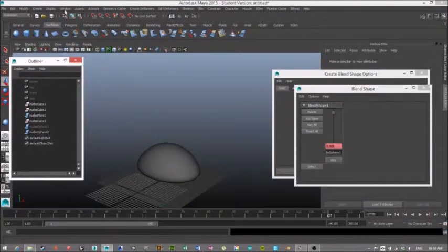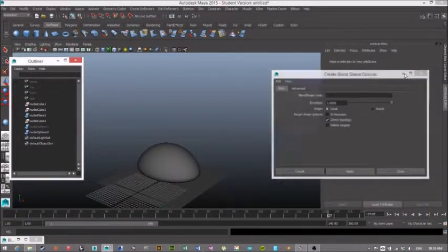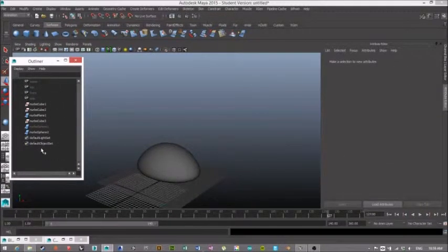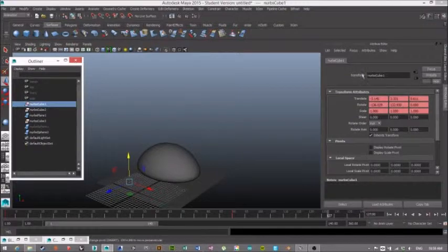this outliner here, if you go under Window and Outliner, it will tell you every single thing. I think we talked about this in the last tutorial, but this will show everything that you have in your scene, all lights, all cameras, all geometry, everything. And you can select on stuff and it'll bring up the attribute editor. And if you notice, these keys are red, that means they are associated with a keyframe, so you can cross-reference and look between the two and figure out what's necessary.